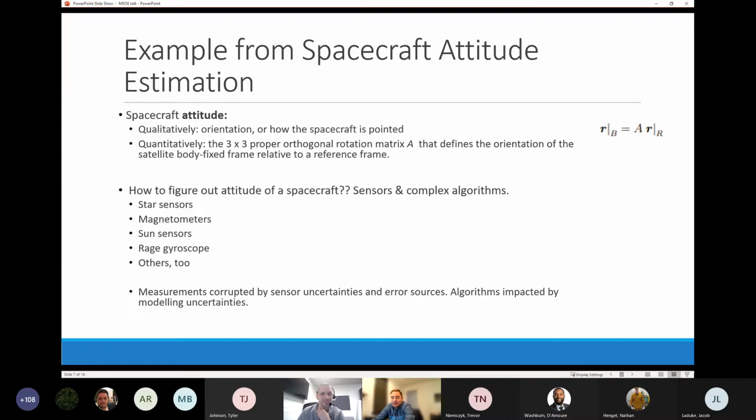So you will actually fly cameras that take pictures of the stars, figure out where the centroids of the stars are, the middle points of the stars, and then figure out where on a star catalog or star map you're looking, and you can kind of back out the orientation of the spacecraft.